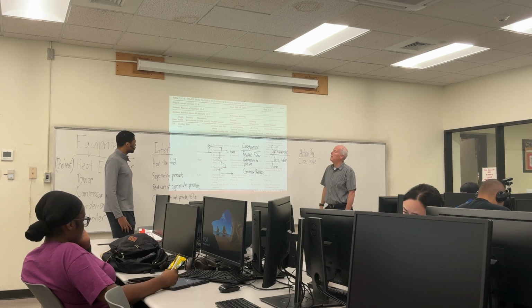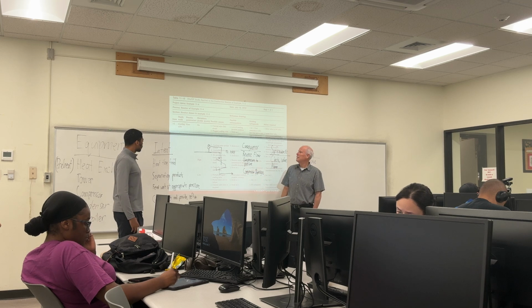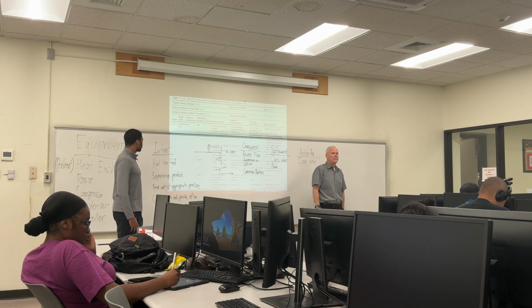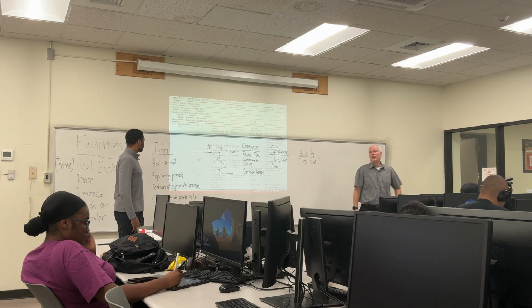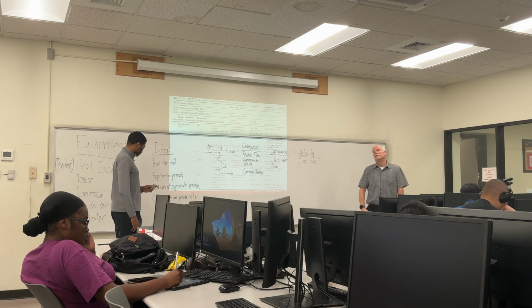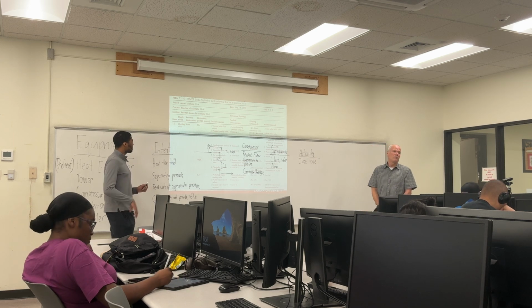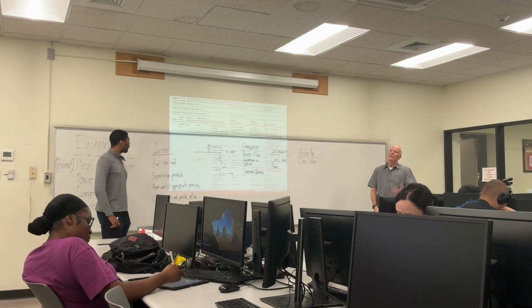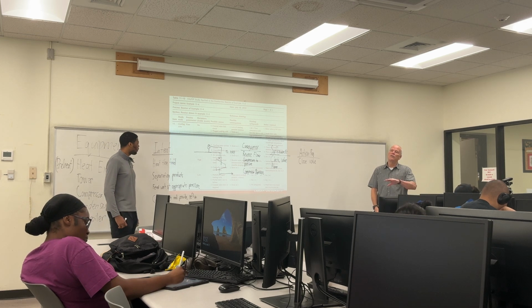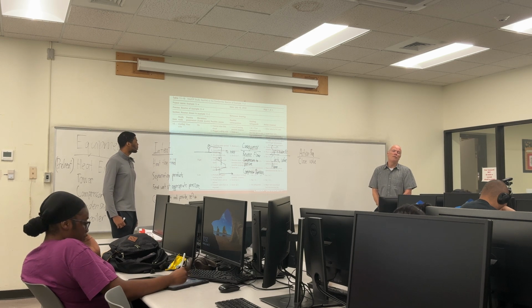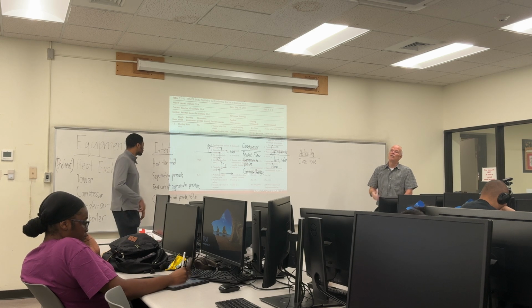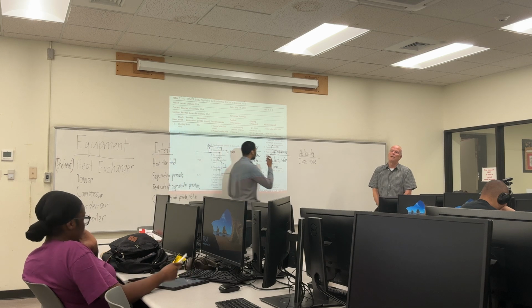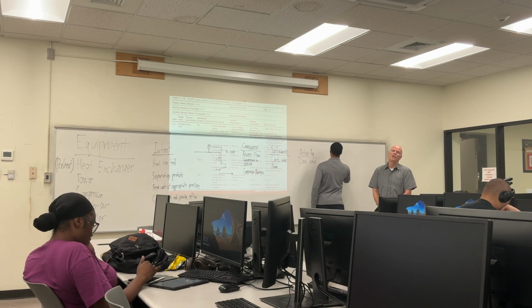So what's the scenario here that causes this thing to stop working? Electrical failure inside the compressor. Well, what's the driver to your compressor? Steam turbine. Yeah, if it's big enough, we saw that, right? If it's a small compressor, it could be an electrical motor. If it's a big one, it's almost certainly a steam turbine. Like I said, there's a small ethylene plant in Groves that uses a gas turbine.